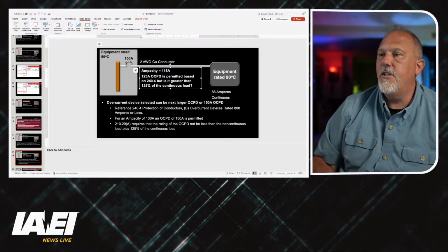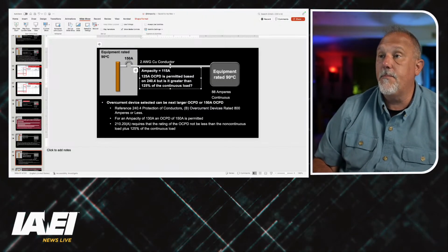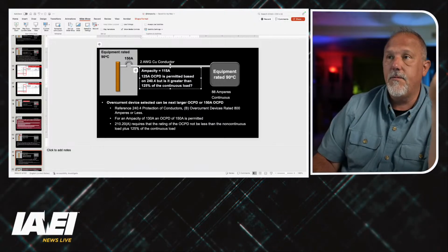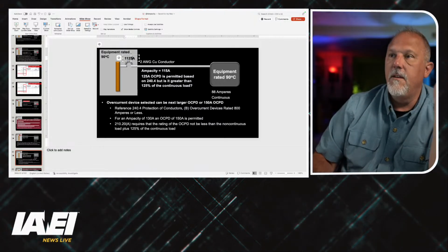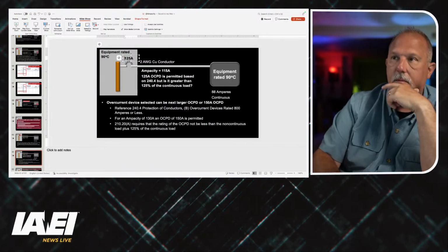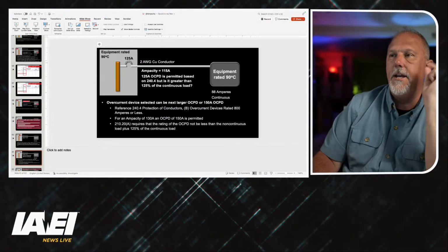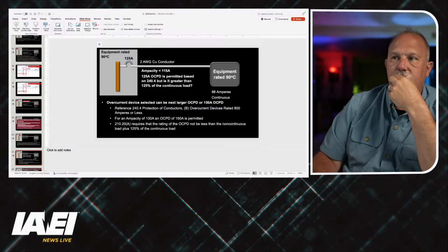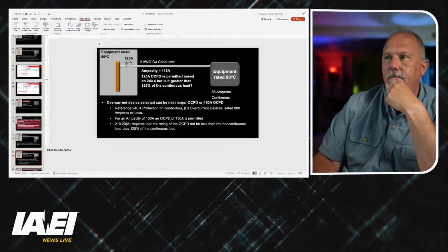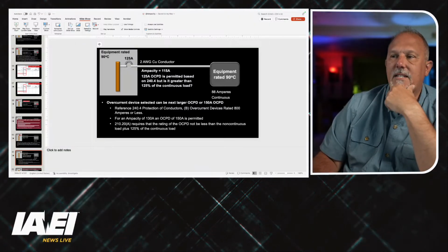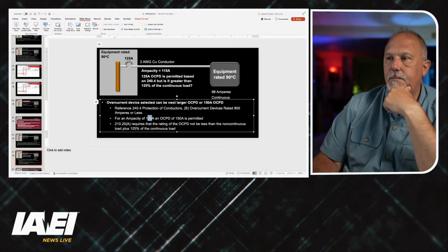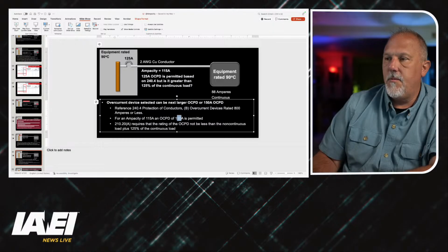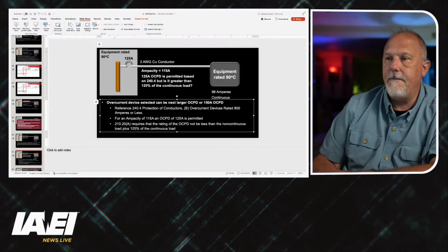Is 125 amps greater than 125% of the continuous? Let's go 125 amps. There we go. 2 gauge, the ampacity of that circuit is 115. I have to protect it at its ampacity. The next higher is permitted based on that, so for an ampacity of 115 amps, a 125 amp breaker is permitted. We know that.